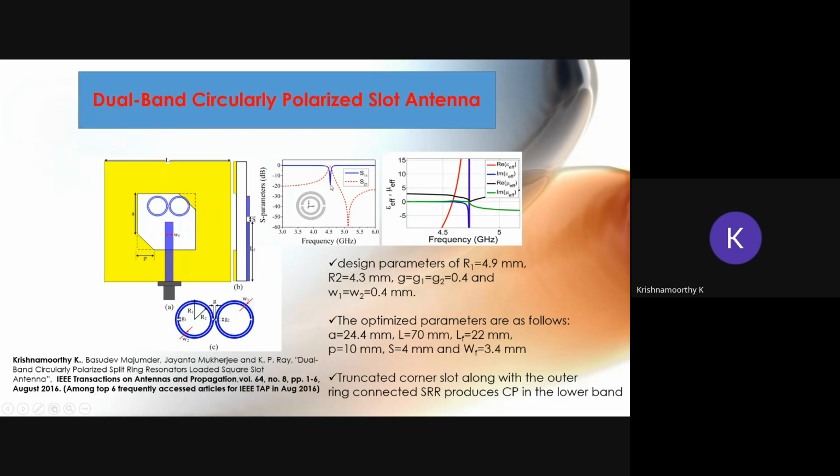Okay, the split ring resonators are characterized for a particular resonance frequency. So whatever the resonance frequency we need, the antenna should resonate at it. So we can characterize the split ring resonators. We can adjust the ring radius and the gap width and all those things, so that we can get that particular resonance frequency. So we have designed for 4.5 gigahertz. Okay, this is the characteristics of the split ring. This split ring is loaded with the simple microstrip slot antenna here.